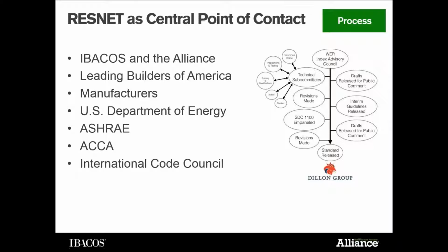Yeah. So we talked about a reasonable set of criteria. As part of this process, we'll have to define what that is. And when IBACOS worked on the TCPI, the Thermal Comfort Performance Index, I think is what we had called it, we talked about the percentage of time within a comfort envelope, recognizing there's going to be time outside of that, and that's okay from the sense of trying to get the bulk of hours in it.